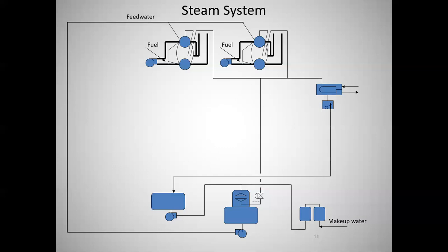The higher the pressure, the better the water has to be in order to not cause problems, corrosion, scaling. If you put minerals in, and the concentration of the minerals gets too high, they will eventually scale out on your heat transfer surfaces. So lots of bad things happen if you don't properly clean up your makeup water.